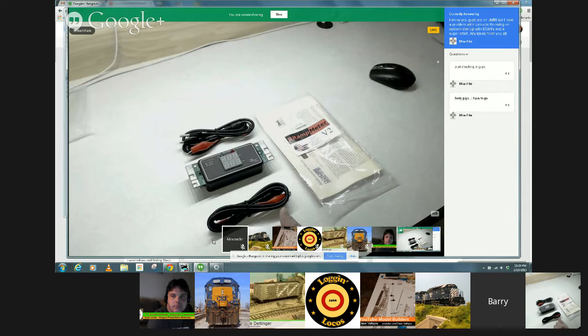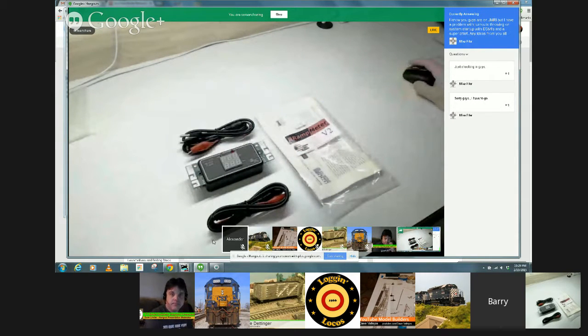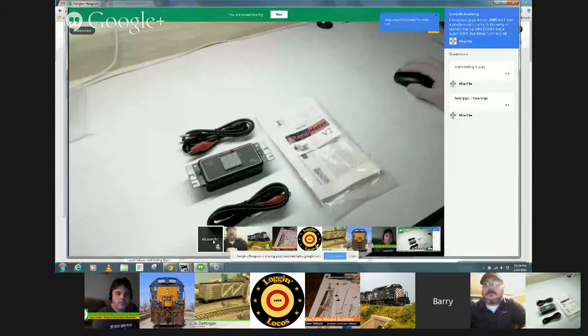Yeah, but I guess what I would need to know from Mike would be, does it happen when he starts JMRI or when he starts the Super Chief up? Because if it does it when he starts JMRI up, he probably has a startup script set that initializes his turnouts. When you build a layout like this in JMRI and PanelPro, when it comes up, it has no idea of the state of your turnouts unless your turnouts have feedback to JMRI.